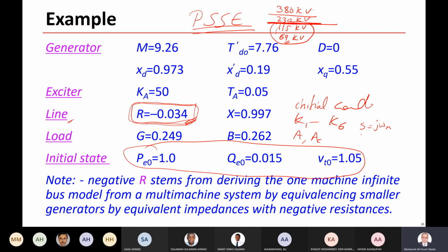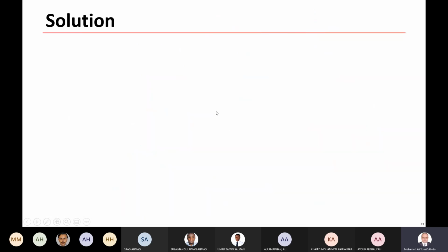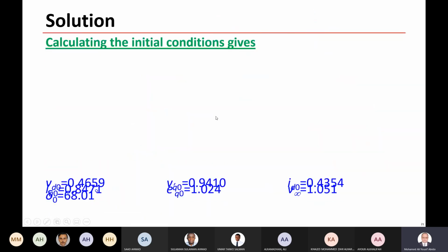You can get the angle of GE and the angle of GC, and you can design T1 by selecting T2 equal to this. TW you can set directly, and zeta n equal to this, so you can get a KC. You can easily design the power system stabilizer and check the closed loop eigenvalues. This is straightforward.